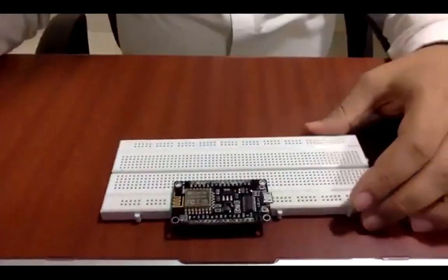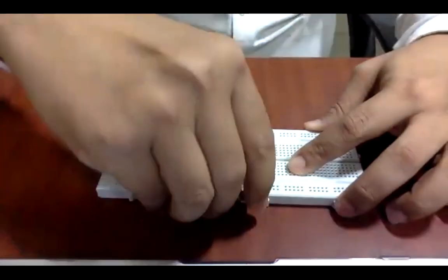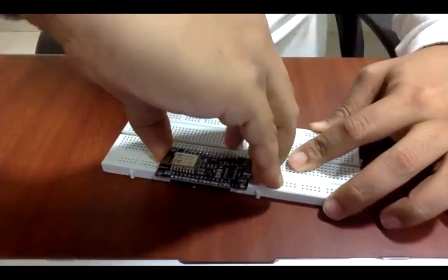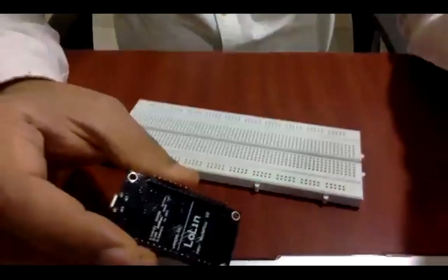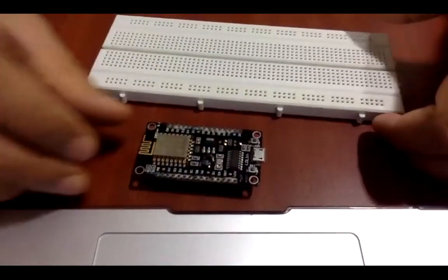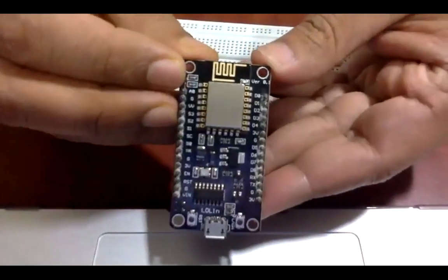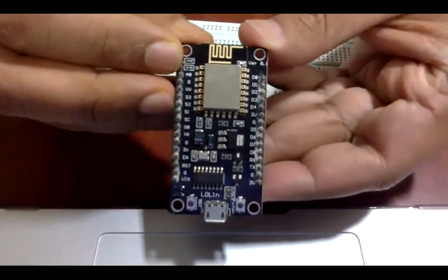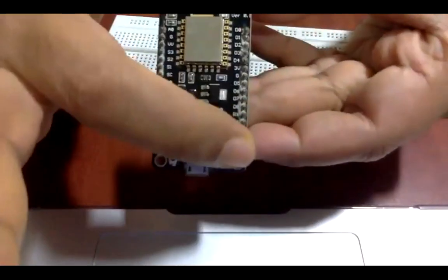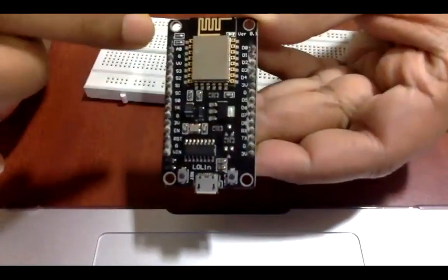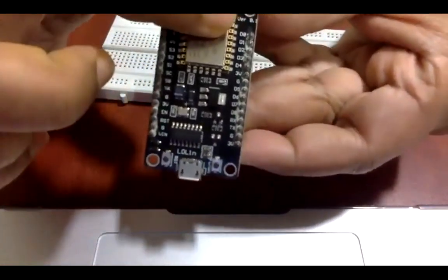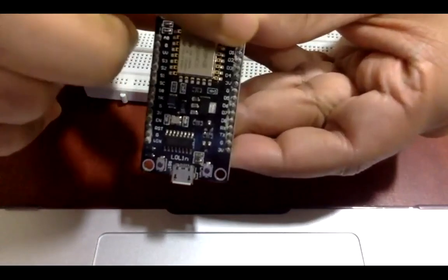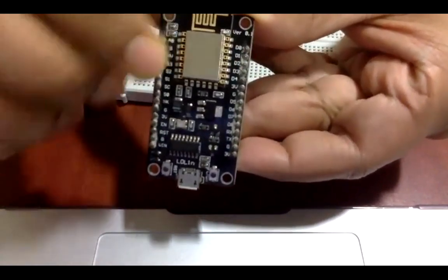So as you can see here, I have this NodeMCU. This is my NodeMCU with us, okay? And you can see the numbers it has: we have D0, D1, D2 in that way, then A0, and there are different pins. Now what I require is that D1 and D2 will be connected with the LEDs.